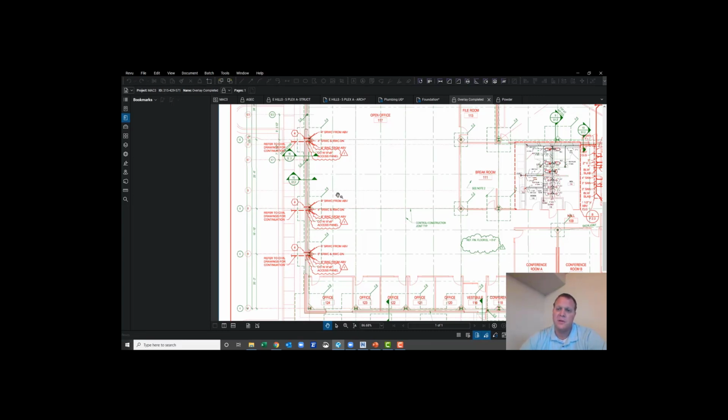One, because they don't want to do litigious things, or maybe they just don't have the experience, or maybe they're lazy. But in my opinion, it is the general contractor's job to try and get the trades to coordinate. And we have something called a subcontractor coordination meeting. So that is something that should be talked about. We're working in this area. What do you guys see that could be a coordination issue for you in this area?